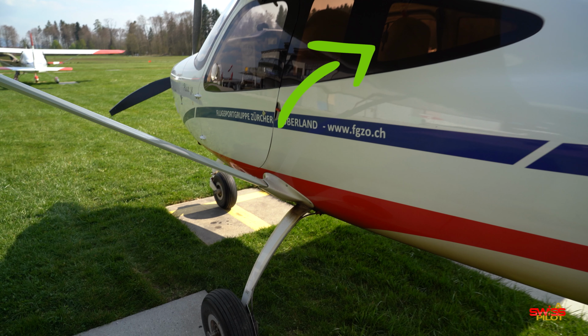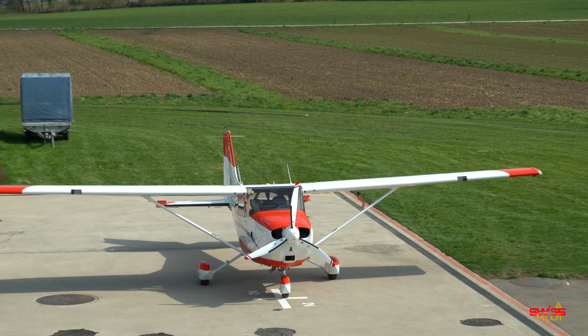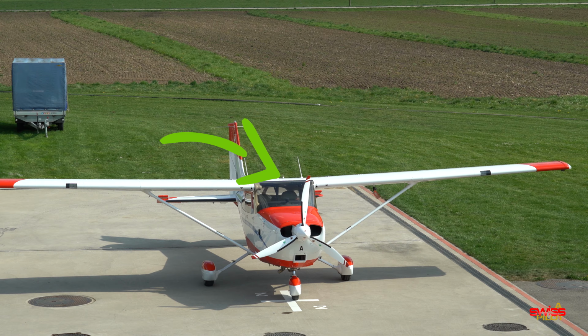I can talk from my own experience. In my aero club we have 3 Tecnam P2008s with a FLARM system, with only the little interior antennas that are mounted to the side windows in the cabin. With this method, the system is not really reliable, if not even rubbish. Sometimes you receive signals while sometimes you don't. We have the same base unit with 2 external antennas mounted to the belly and the top of the club's Cessna 172s, and that's actually a big difference. The way the whole system works is a lot more useful and a lot more reliable.